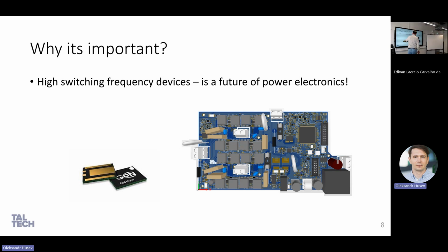But this is a typical example. It's from our design, but it's a typical PCB, which includes digital and analog circuits plus power electronics. This is so-called mixed signal PCB design. Mixed signal, what does it mean? That you have all types of signals or different paths or currents that you have to address. And electromagnetic compatibility must be addressed, first of all, inside this PCB.